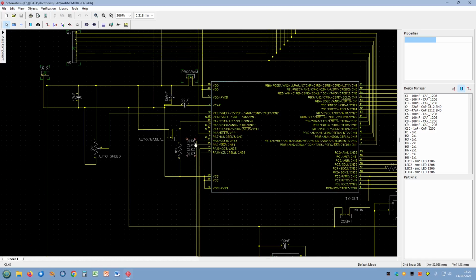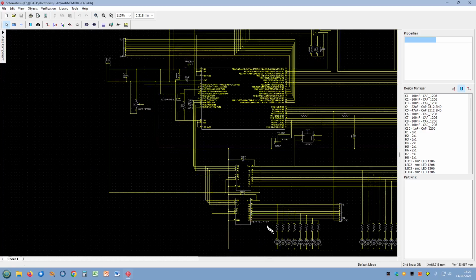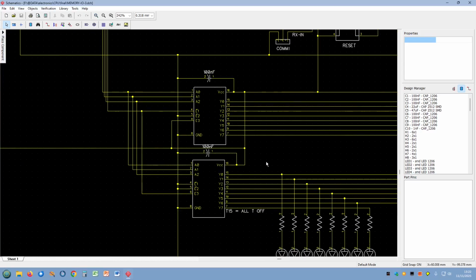Now, just below that, we've got clocks 0, 1, 2, and 3. These are for the T states. So there's a possible 16 states there. And if we look at the 74238s, there's 2 of them here. So A0, 1, and 2 is wired the same on both of them, because these are 3 to 8 decoders. We've also got these enable signals. So the false signal, the top clock signal, on there it's not enable, and on here it's enable. So it's that chip or that chip.